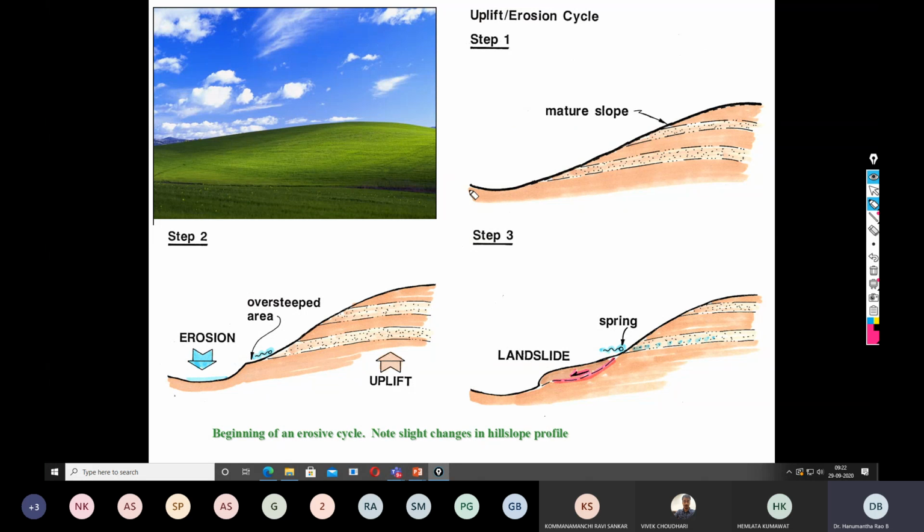Because of the erosion, here you can see initially this was a particular curved shape, but this curve was deformed into another curved shape, causing an imbalance in the original shape. When there is an imbalance, it causes imbalance in some soil mass. Here you can see the erosion caused some kind of imbalance in a certain soil chunk, so this becomes imbalanced. Whenever it becomes imbalanced, it always tries to move or slide on the inclined plane.